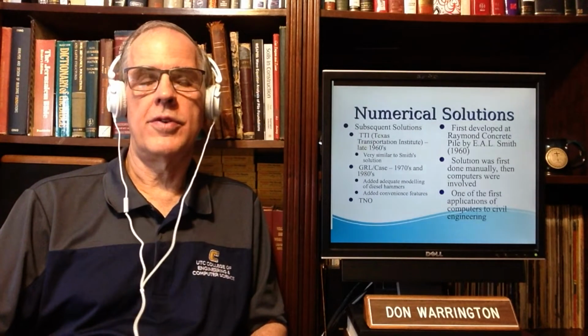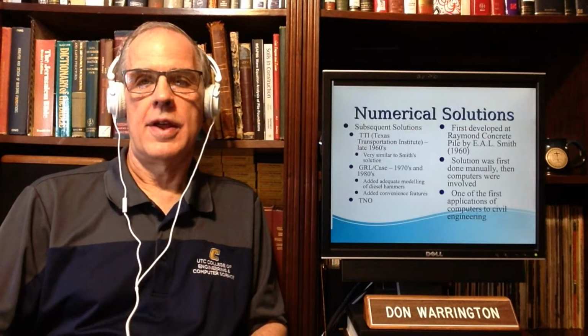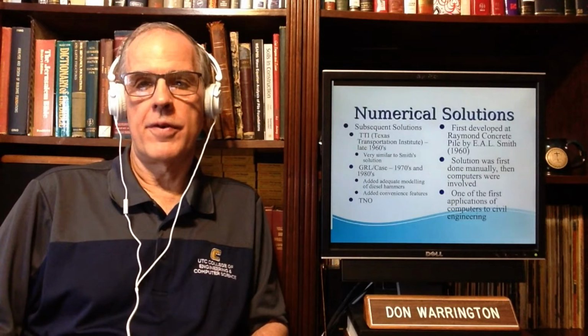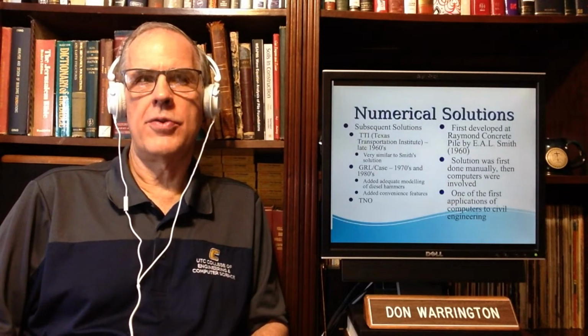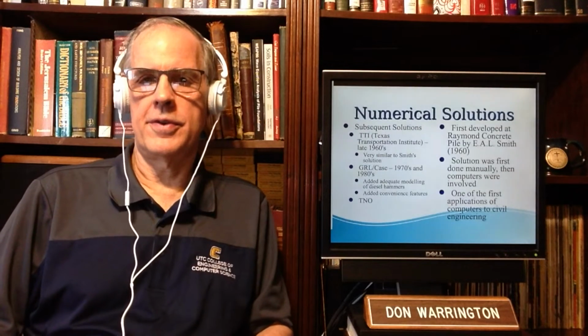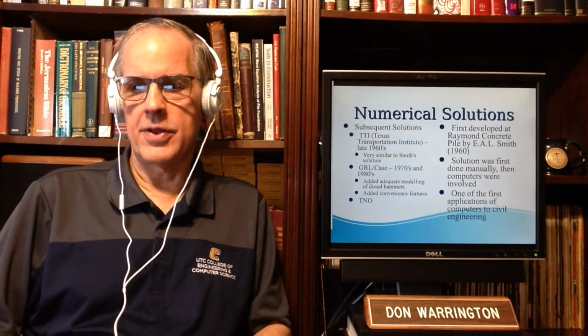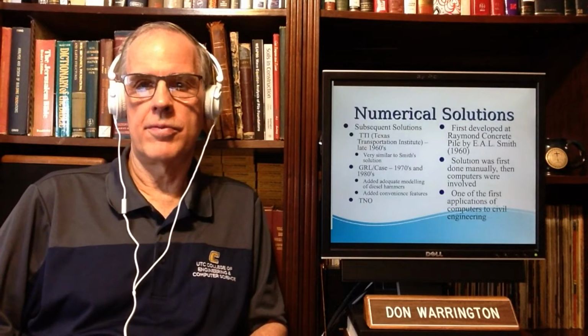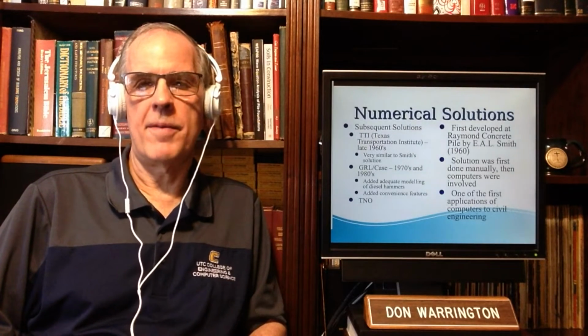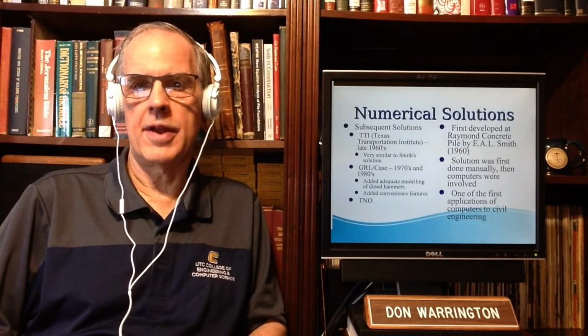TNO is the Dutch organization, and they developed the wave equation in Europe. They use the method of characteristics. It's a little different numerical technique than Smith, TTI or GRL used, who used a lumped mass system, a lumped mass solution.